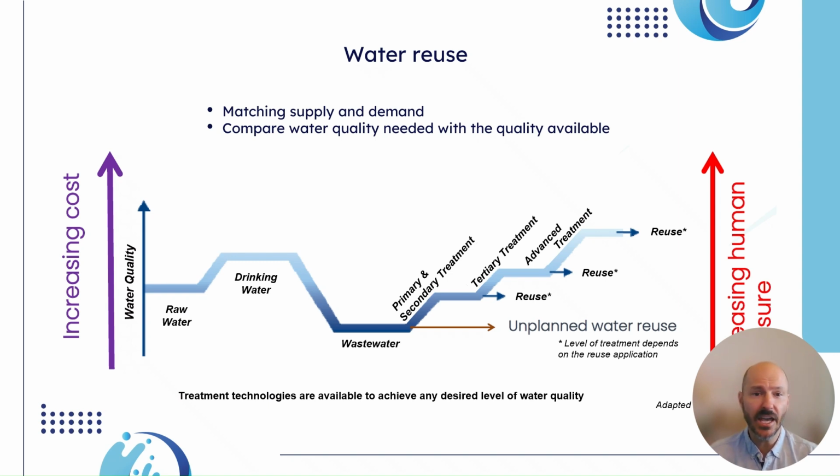Membrane filtration and UV disinfection treatment steps are usually part of tertiary or advanced treatment. Constructed wetlands can be used to provide some secondary treatment. However, they may also be used following secondary treatment in a polishing capacity.